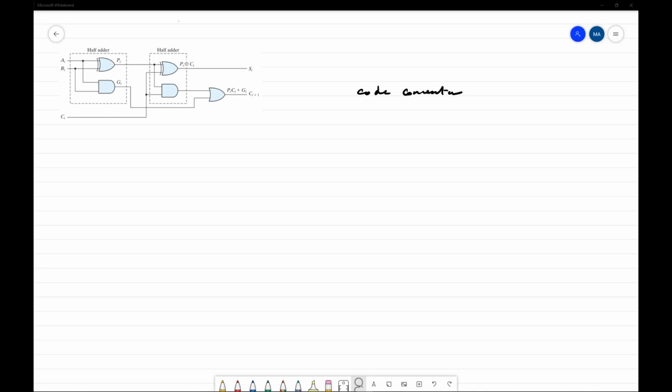And then when it comes to binary additions, we have shown that we can perform binary additions for one bit using two types of combinational circuits. The first type is the half adder, and the half adder is capable of adding two bits at any given time, and will produce a sum and a carry out.